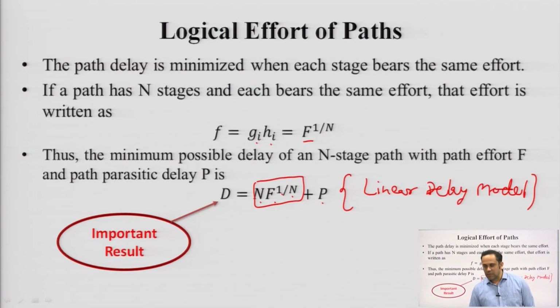So, this was all about logical effort of path. Okay. I hope the concept has been clear to you. The linear delay model, compared with the RC delay model, is simpler, because it uses a simple algebraic equation. If you remember, before the RC delay model, we did what was known as transient response, which involved solution of differential equations, which was even more complicated. So, with each model we have tried to simplify how delay is estimated, how delay is quantified.